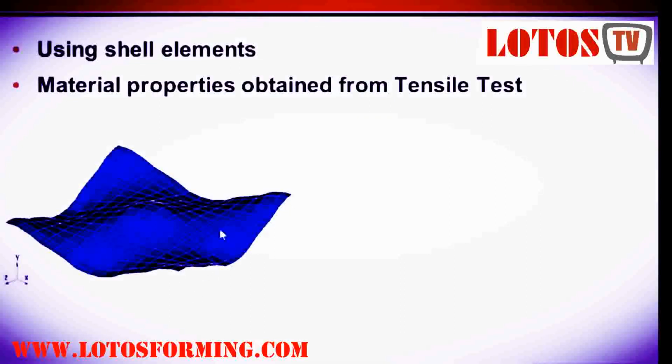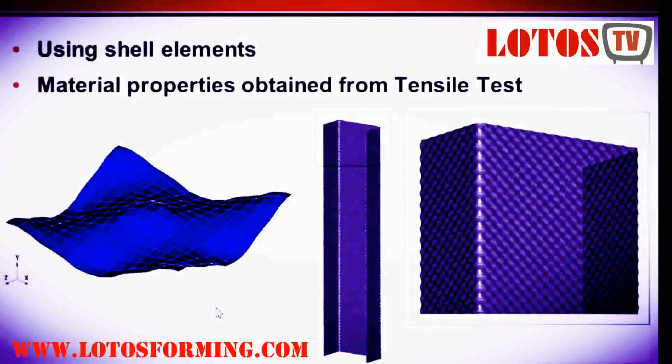By this way we can present this mid surface as a shell element, so that we significantly reduce the number of elements, but still accurately present the shape, the geometry of the dimple. And then we use this generic shell element to develop the large dimple strip and then cold-form it into a section.